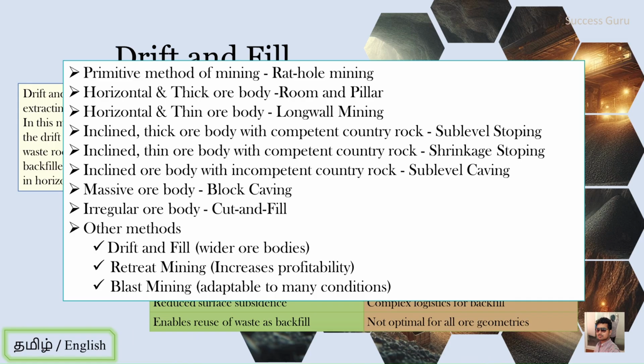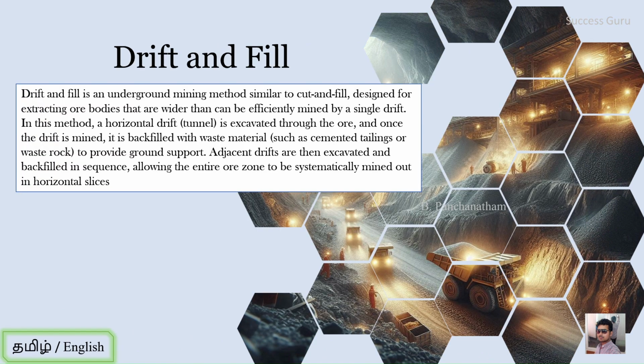So in this video, I'll try to cover the last three methods, that is drift and fill, retreat mining and blast mining. So let us see what is drift and fill. In the topic called parts of underground mining, we have already discussed the term drift, which is a tunnel that is driven on an ore body, right? The drift term implies it is a tunnel driven on the ore body itself, and fill indicates that we are backfilling it after driving the tunnel. This is the basic principle of this method.